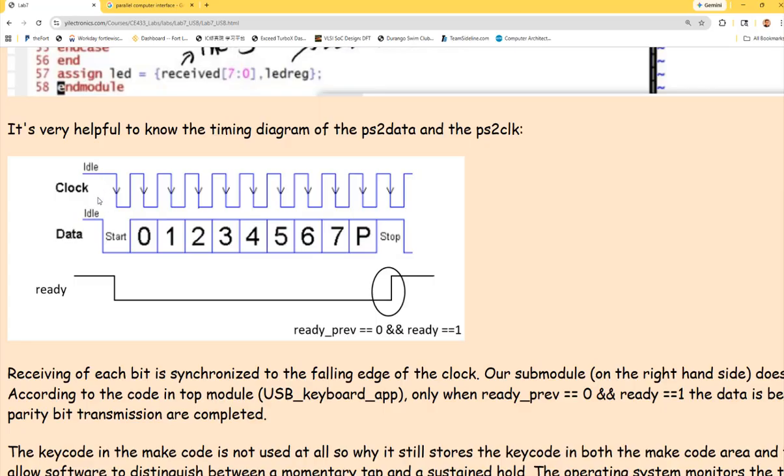So it starts with a 0 as a start bit. It pulls it down, right? Pulls it down. And the clock is a bit different. The clock is not synchronized with the data's edge over here. So what this does is the negative edge of the clock will sample it. The negative edge of the clock samples it. Okay? So that's a protocol directly from the chip.